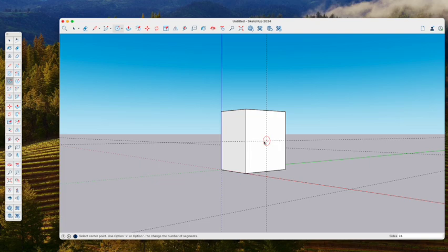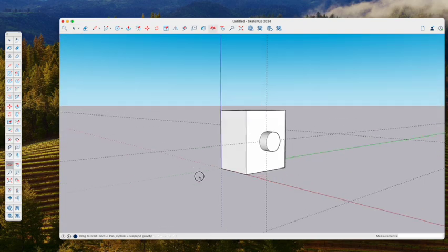All right, so making the little pipe out, we're going to go from the intersection. See, if I'm there, it's on the line. Here it's on the face. Here it's in the intersection. Once again, you see how it's blue, green, and then black. It's in space. So we want it to either be on the face with green or on the face with blue. Doesn't really matter how big it is. We'll do like so. You could pull this out or you could pull this out. Let's make it a pipe and pull it straight out, not so big. You can make this into a component, yada, yada, yada. I'm not really sweating on that.